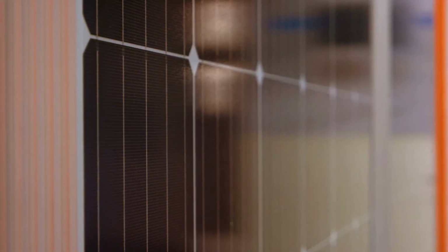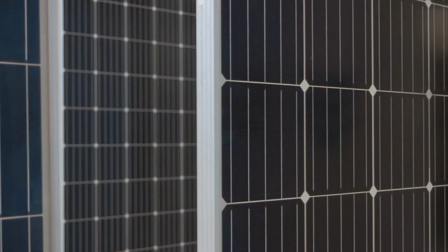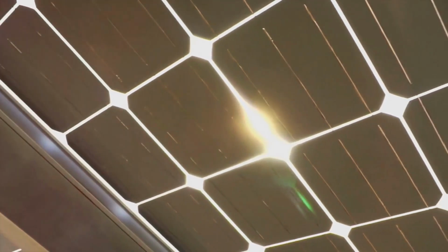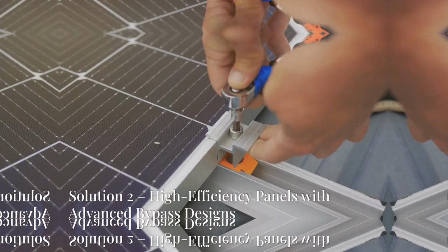Most traditional solar panels come with bypass diodes that allow groups of cells to bypass shading impacts. For example, a standard panel might divide cells into thirds, each with its own diode. If one section is shaded, the diode allows electricity to bypass it, reducing the loss but not eliminating it. Panels with just a few bypass diodes per panel are generally cost-effective, but they don't handle complex shading situations well.